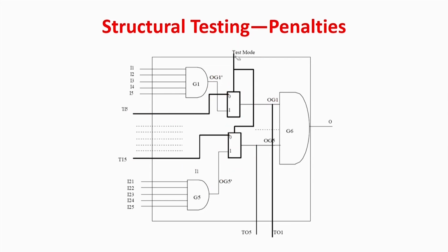But when I am operating in the normal mode, you make the test mode equal to 0. In the test mode it is equal to 1. So in the normal case the external lines will be cut and the output of this gate will be fed to this gate and your job is done. That is, you can apply some patterns directly to these inputs. Again, as I have already told you, I also have to explicitly observe these lines when I test these two gates. But how do you observe? Again you can change the configuration mode, and the output from this can be observed on this line.